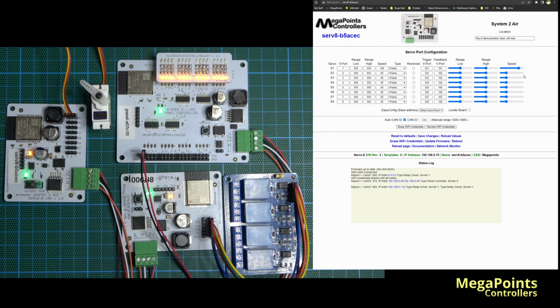If I slow that servo right down, you'll see that the flashing is correctly indicating the state of the motor. So you would use that. Say you had a gate, a barrier, or a set of points that you were moving and the motors were moving slowly, then it's important for the panel to tell you that there's something going on and it's in motion. Also, I find that useful where you've got multiple panels connected and a remote panel where there might be an operator. It would draw their attention to the fact that that particular accessory is moving.